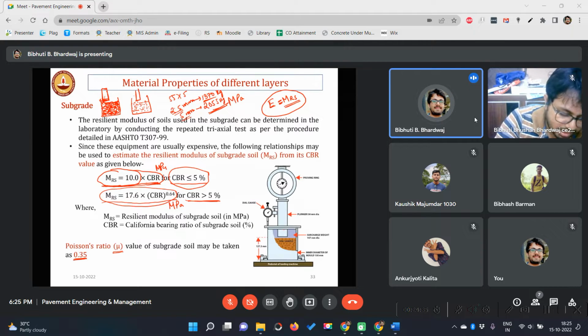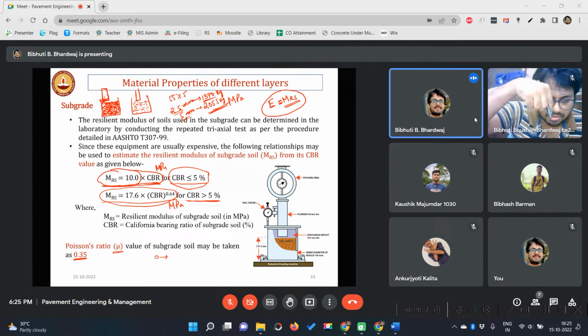Now suppose you have your own soil collected from your site. You compact it using the same method. Now you try to penetrate the plunger, reading your penetration with a dial gauge and also the force you are applying. For 0 mm penetration, you don't require force, right? For 1 mm penetration, you need some force, say 100 kg.